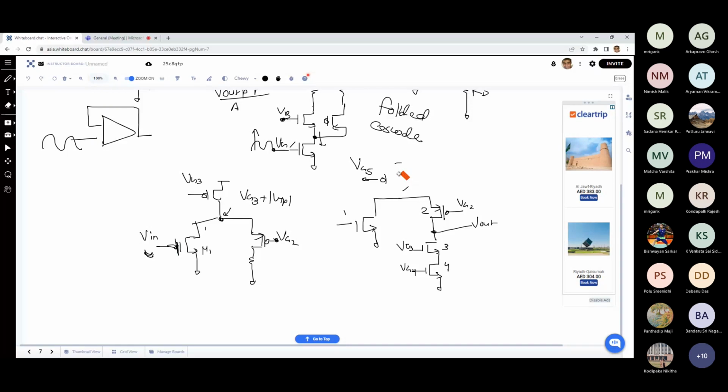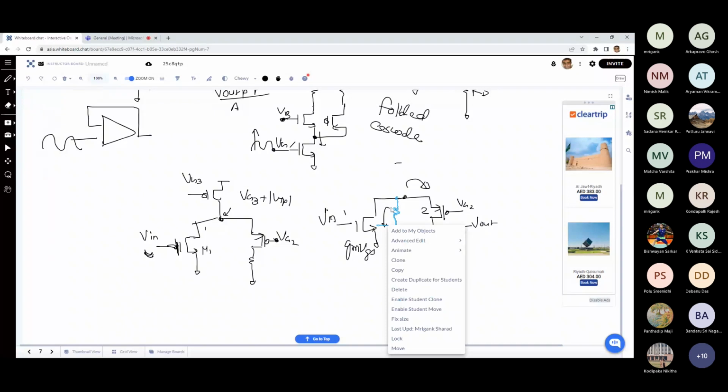And if I ignore this, then I have the small signal current, basically whatever is being produced by this one. I had the same logic here. Impedance looking into this, what will be the value? Because now again I have to divide the small signal current. This is the V is applied, the GMVG is being produced, and now the lower branch, of course, you will have the RO of the M1, and I also need to look into the MOSFET M2's impedance looking into the source. So this one is anyway same as RO1.